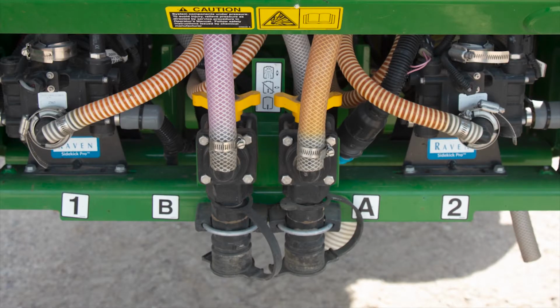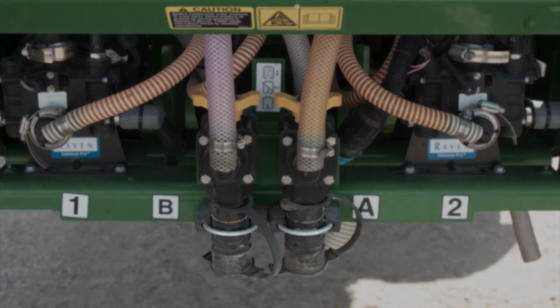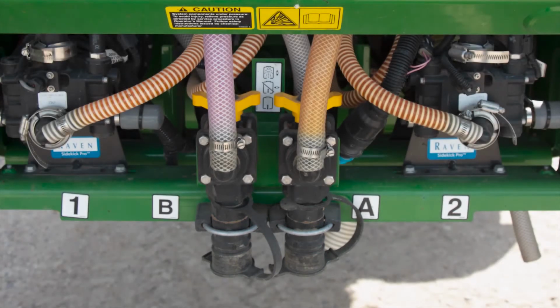And another last nice feature, when loading direct injection, those valves by default, we typically mount them in the back. Some people will mount them off to the side. It's really operator preference, but they use a flush fill valve from Banjo. So it's a no drip valve. You essentially take the end off of your bulk tote of chemical, put on this flush face, and it clicks in. You load up as much product as you want. When you unhook, you just pull down on a collar and it will disconnect without dripping any product on the ground. So a really nice option there.